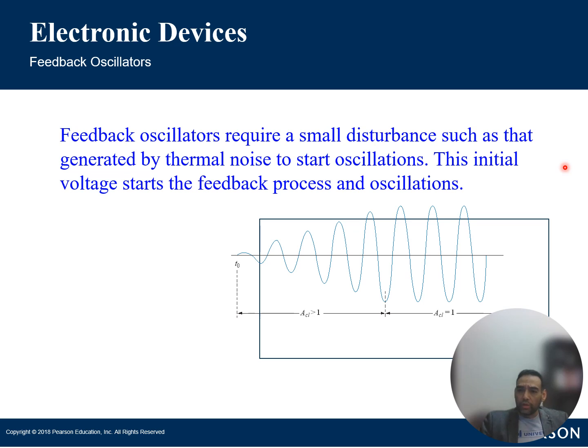So what we do is we use techniques such as shielding, filtering, and isolation techniques, and you want to use those to minimize those external interferences on the oscillator circuit. And then once you've done this redesign of your oscillator, you test and you verify. Right? Always test and verify. So you thoroughly test the oscillator. You put the circuit under various operating conditions and ensure that it remains stable, reliable under those small disturbances.